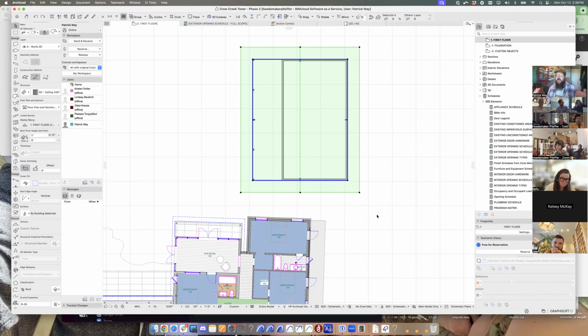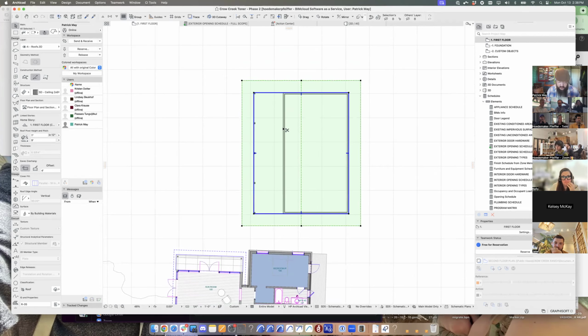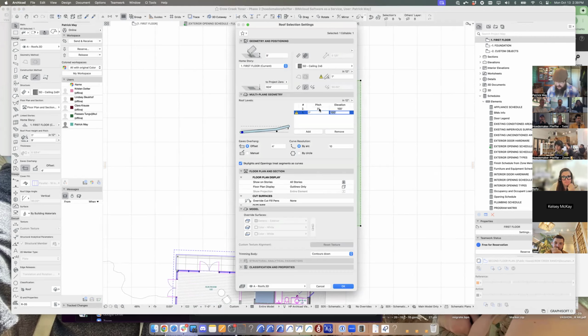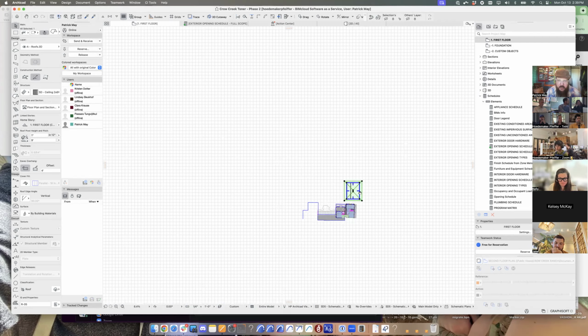I mean, even if you had, let's say, a gambrel roof or something like that, or a pitch break, there are settings in here even where I could say that we go from a 1 in 12 to a 3 in 12 pitch, right? And then it creates, there's a guess and check aspect to this. So let's say that that's there. I'm not seeing where that's at though. It should have a pitch break option in there.